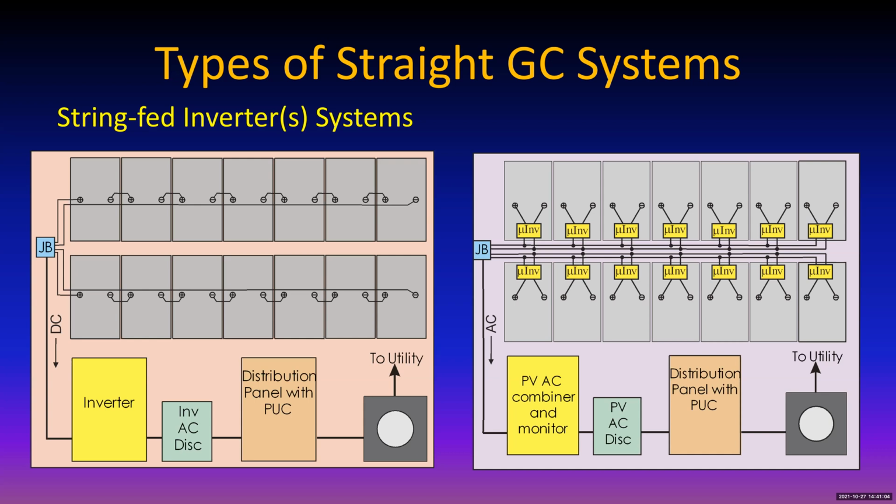Now, these 2 rows then are connected in parallel at the inverters. The significance here is that anything connected in parallel will have the same voltage. So these 2 rows must have the same voltage. Anything connected in series should have the same current, and indeed they will have the same current, and they will adjust accordingly.